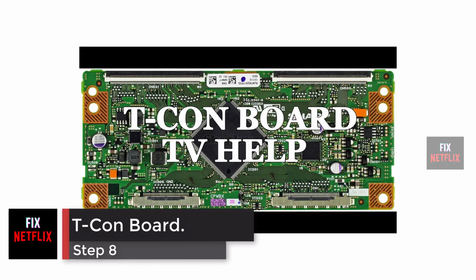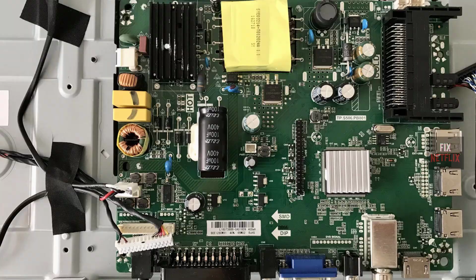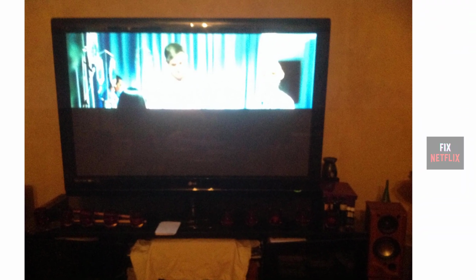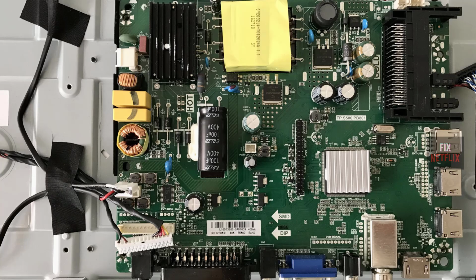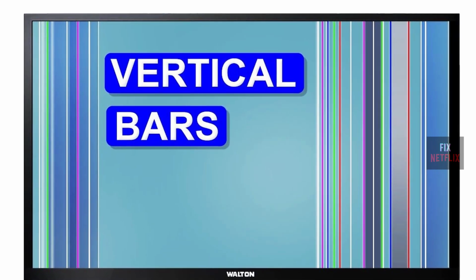Step 8. T-con board. This check for the T-con board also touches on the condition of the main board. Note that problems that show up on half of the screen, like bars or such, point to a failed main board, as the T-con board errors show up on the whole screen. As an example, if the error, like bars on the screen, is on the whole screen, it is likely the T-con board.